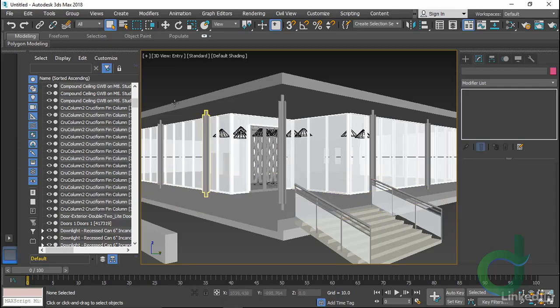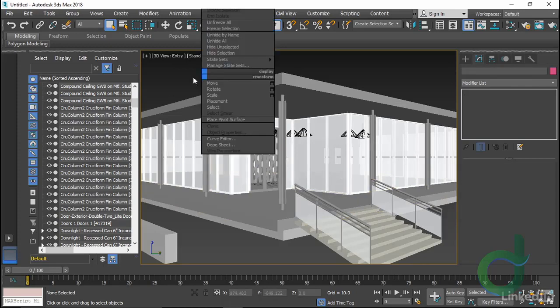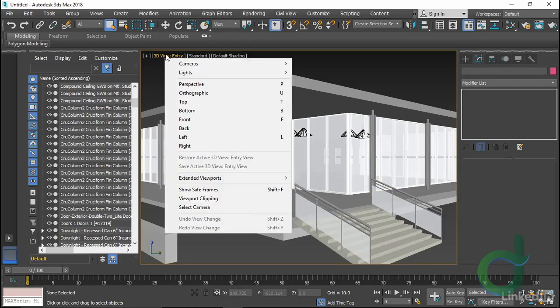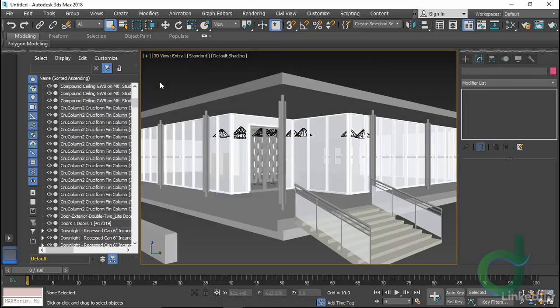Pressing C for camera takes me to that entry view I had set up, and then clicking on the 3D view entry allows me to choose that camera or another view. If there are multiple cameras that were brought in, showing in Revit, we could bring them across. At the moment, I only had that one view, so that's what came in, baked as part of that FBX. My lights came in, off at the moment, and shown as these black cones.